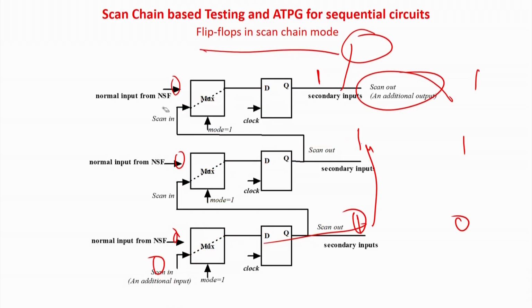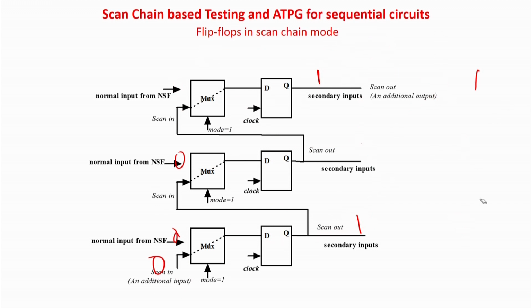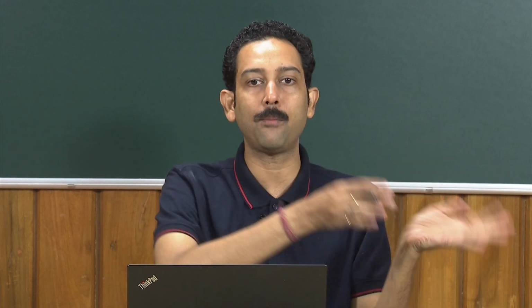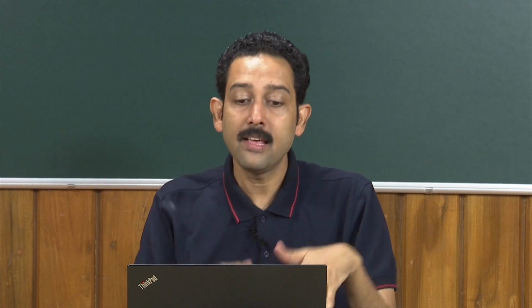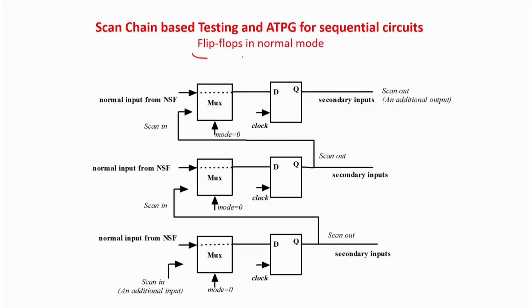But this single scan chain actually solved problems for many years before moving to more complex circuits. Because as you can see, it is a simple scan chain or simple register, so the delay is very less, because one flip flop is connected to the other and so forth. From digital fundamentals you can apply a very high clock speed to transfer the data, because the delay is almost negligible, as there is no combinational circuit in between. So the scan data can be fed very fast. And now, when the scan job is done, basically you can see the flip flops are in original mode.